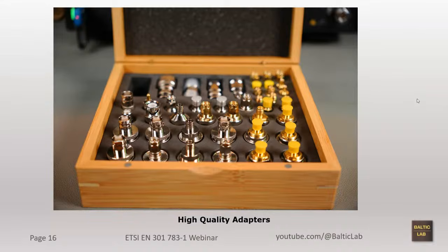You will need that. You have accurate insertion losses on the data sheet that you will later on need to correct. And the most important thing is that it's also constant over a broad frequency range. If you just measure at one location, nobody guarantees you that the same behavior is present at, I don't know, 4 or 5 gigahertz. So please do that, or at least verify the cheap stuff you got on Amazon.